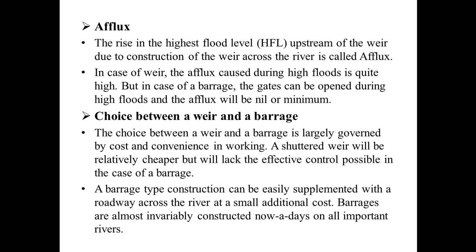In case of a weir, the efflux caused during high floods is quite high, but in case of a barrage, the gates can be opened during high floods and the efflux will be nil or minimum. In weirs the efflux is high because there is very little control over the river water, so when a flood comes in the river, the water level rises to the highest level and efflux is maximum.